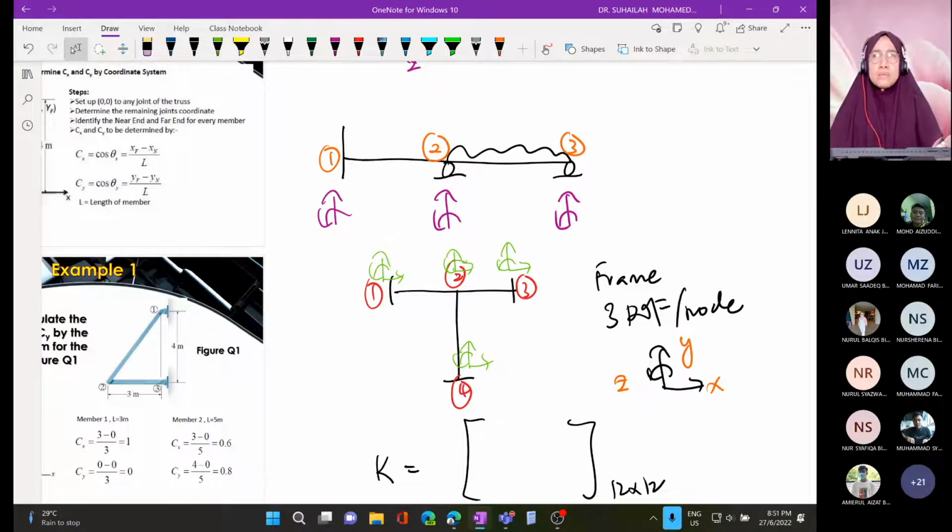To get displacement in an indeterminate structure using the flexibility method, we have to apply the unit load method after we have solved all the reactions, at one point at a time, so 1 by 1 point.